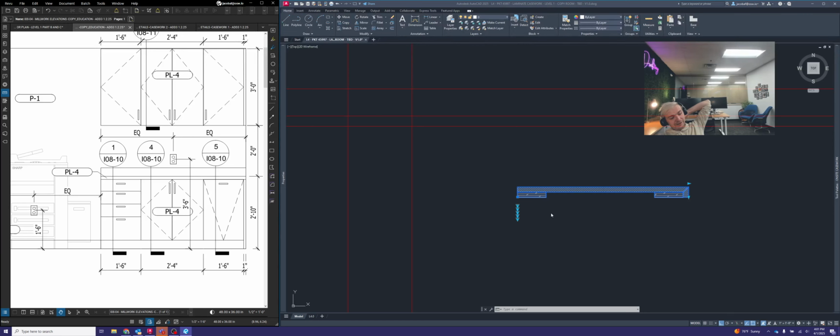Now, we don't have anything like that here. All of our countertop is being supported by the cabinet, so we don't have to worry about using anything other than subtop strips here. Moving on down this, we actually don't have ledger either. Ledger is utilized sometimes for floating counters, or if you have a counter that spans over an opening like a refrigerator, you can use a ledger to help support that countertop.